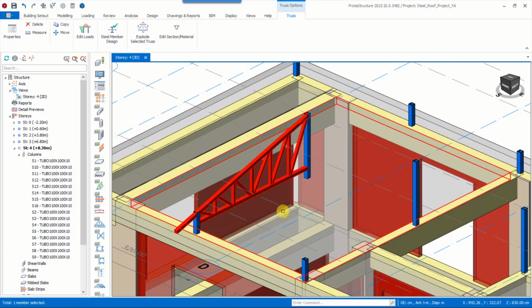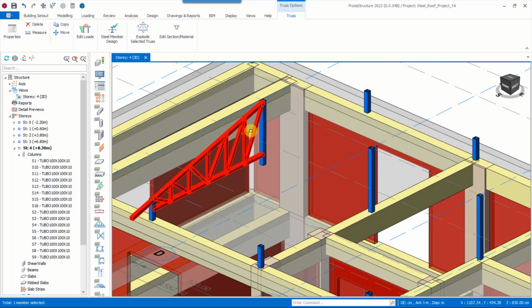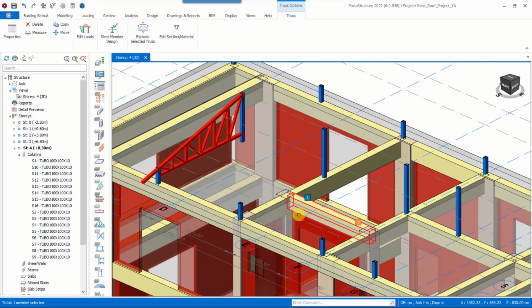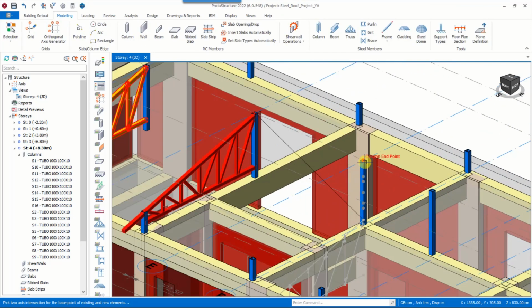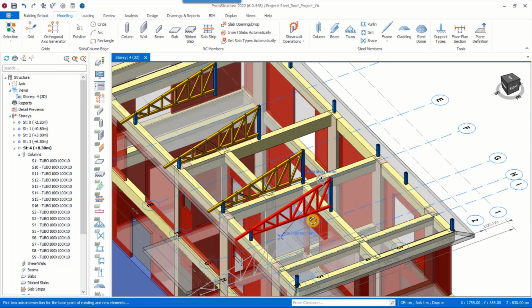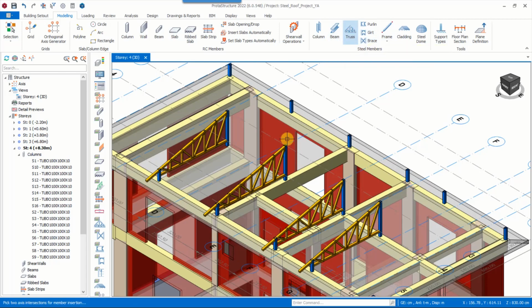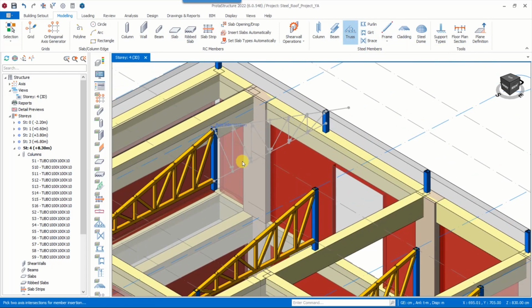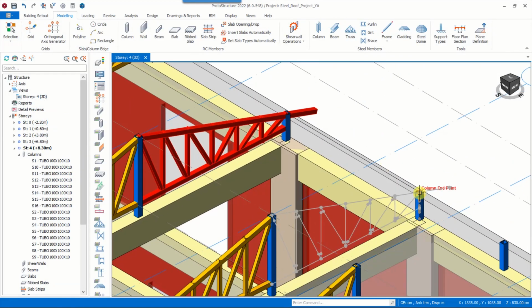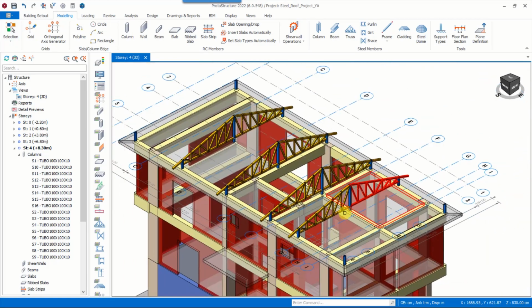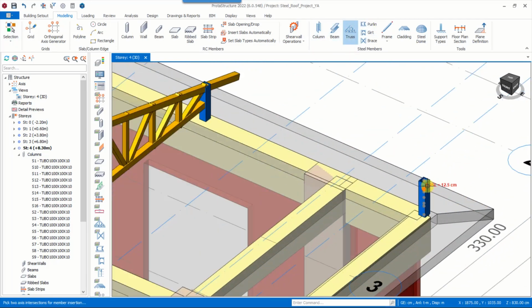After completing the adjustments on properties, we can start inserting the trusses now. The trusses can be inserted by either selecting the columns to be at the ends of the trusses, or using the copy and paste commands. Since the last section settings are still active, we can directly insert the truss and copy this one for the rest of the trusses. We need truss members at the corners as well.